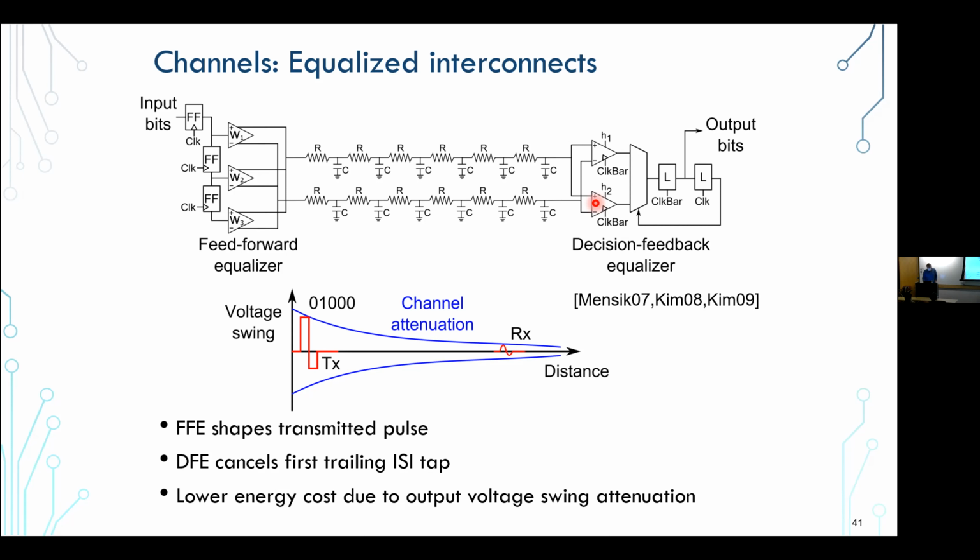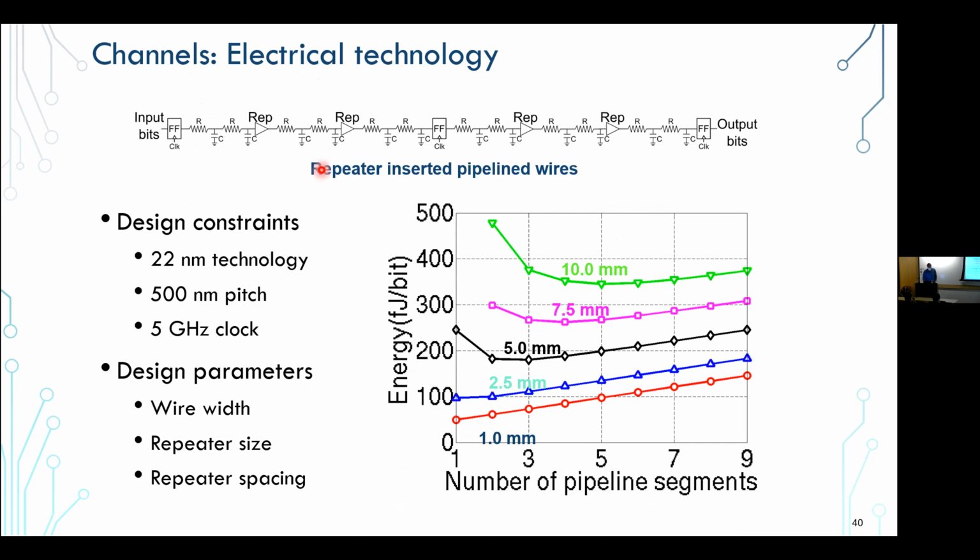It also goes to say that, if you're implementing something like this, you don't really have to run these repeaters at full voltage, right? Depends on what clock cycle you chose to signal at. All the voltage scaling, low swing kind of things that we apply to logic, we could apply to these repeaters as well to be able to reduce the overall wire energy.